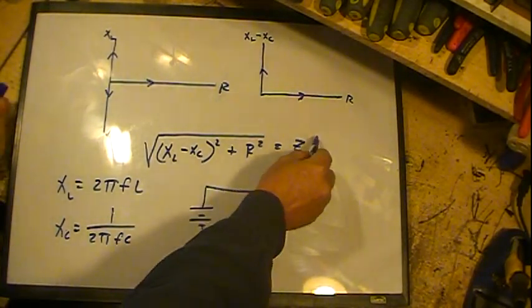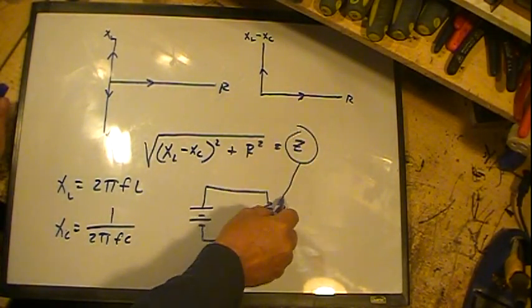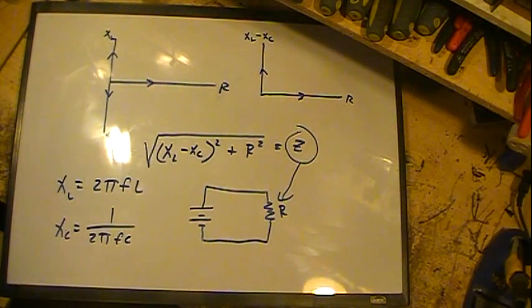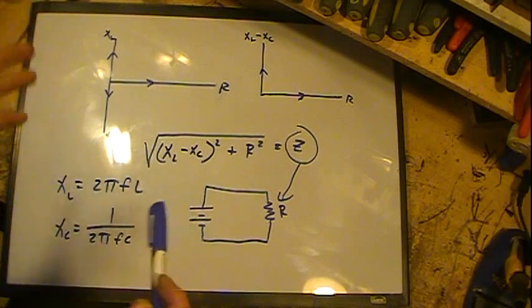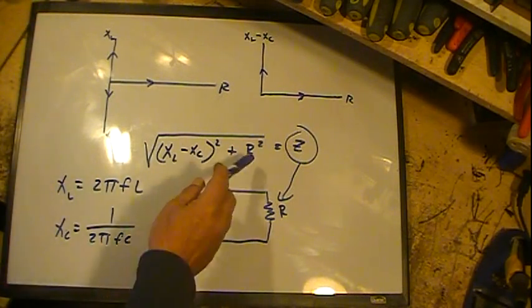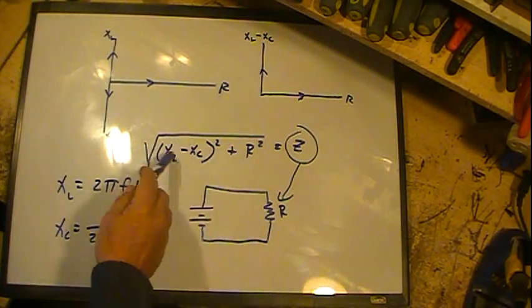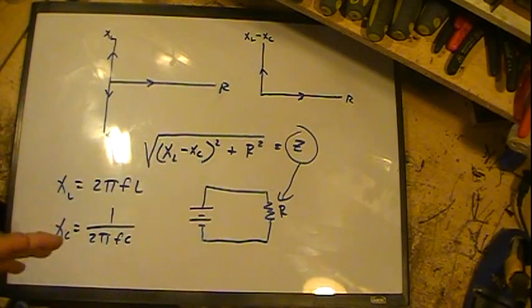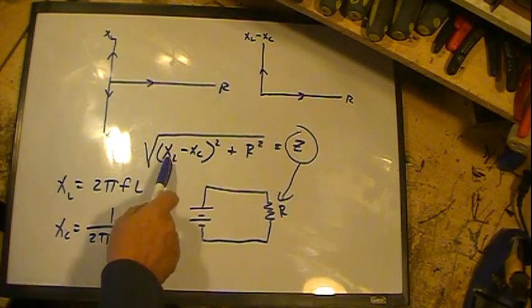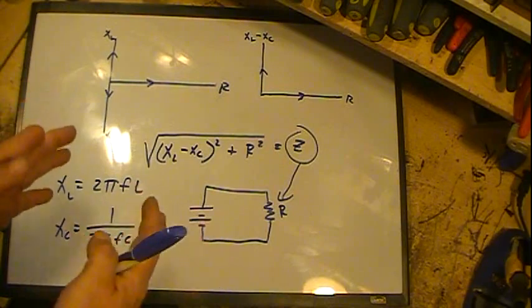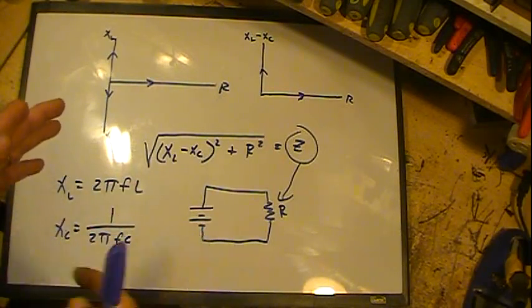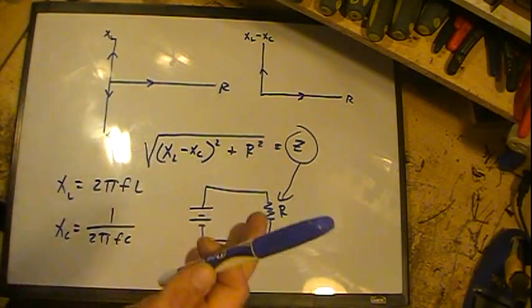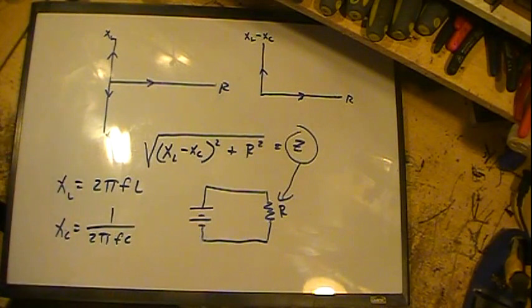Well, impedance literally works the same way as resistance, except in AC. I mean, you can use it in DC if you want, but in DC you only have just the resistor. These two have no effect on DC as far as any type of resistance or loading in there, other than the fact the coil will have a certain amount of DC resistance because the wire has resistance, and the capacitor just blocks, so it matters not.